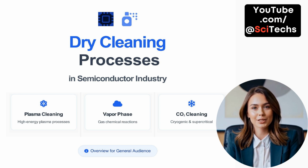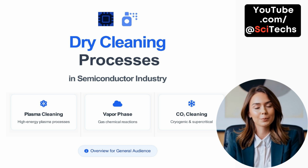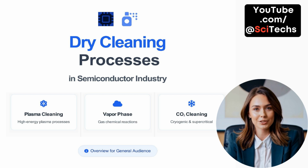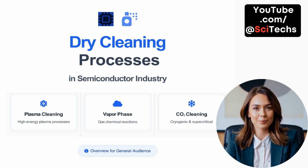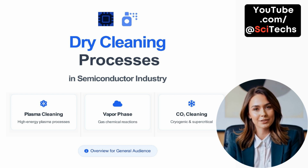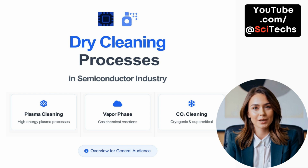There are three major categories: plasma cleaning, vapor phase cleaning, and CO2-based cleaning. Plasma cleaning involves high-energy plasmas that react with and remove organic residues, native oxides, and particles from surfaces through ion bombardment and reactive species. Vapor phase cleaning utilizes gas phase chemical reactions to etch or remove specific contaminants without the need for rinsing or drying steps, reducing water usage and minimizing stiction risks.